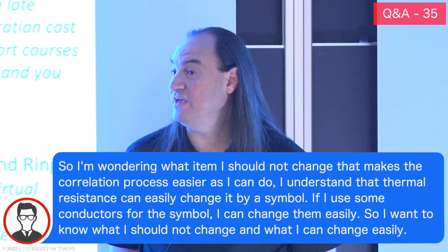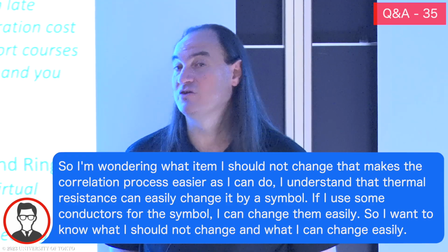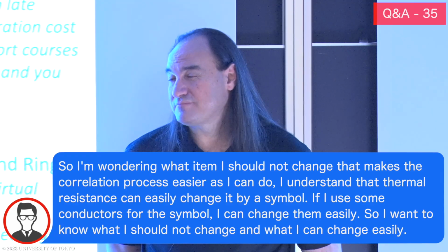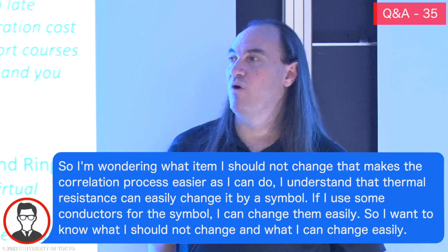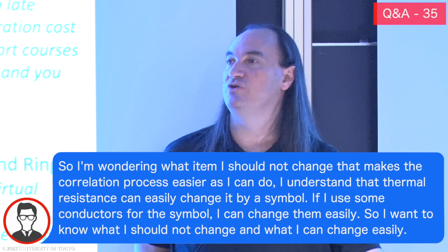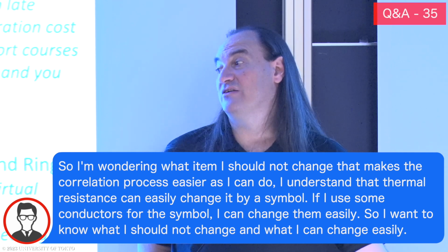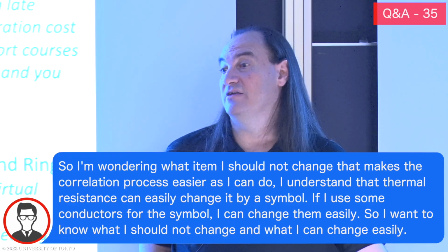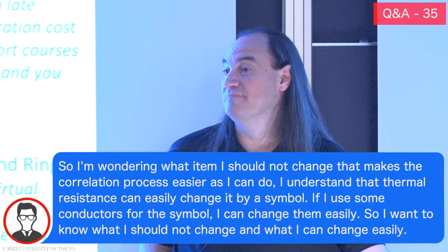Look at the GSE. Is it possible that the GSE is what's causing the problem? The ground support equipment. It's really you as an engineer understanding what the hardware is and whether your model reflects the physics of that. Sometimes it's a simple conductor, other times it can be far more complicated. I have to build this bracket. I can't just say it's a 0.1 watt per K.